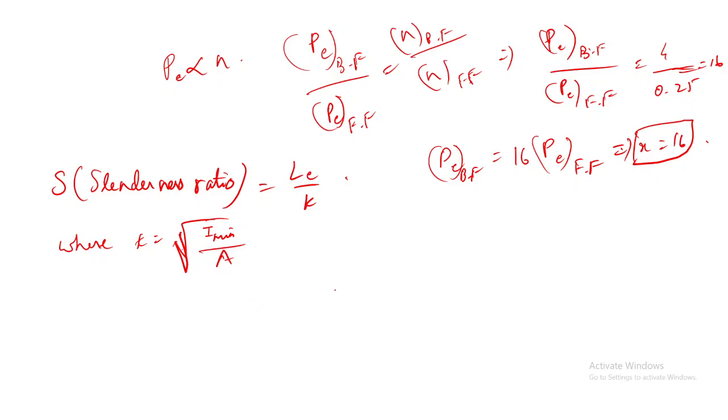So here, can you explain, sir? Okay, that I will explain. Sure. See, for example, the buckling load is PE, correct? If I want to find out the buckling stress, sigma E, it will be equal to PE divided by the cross-sectional area of the column A, correct or not?